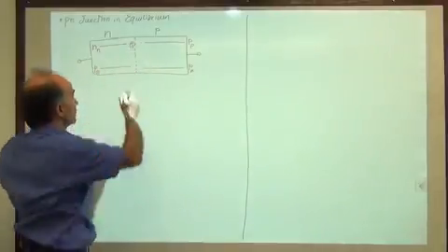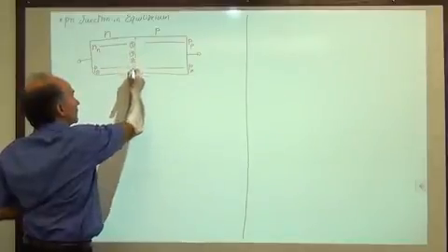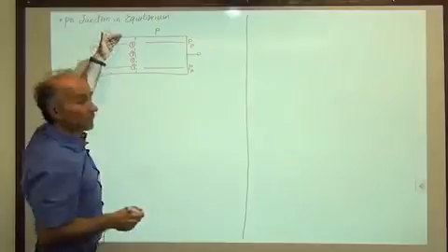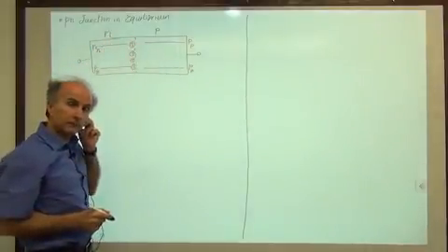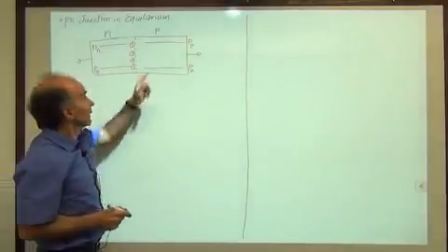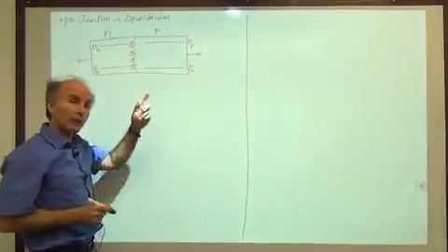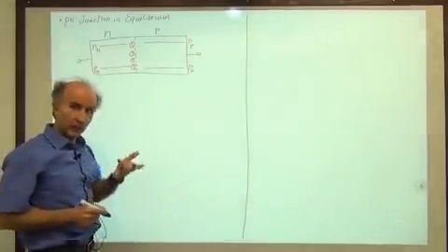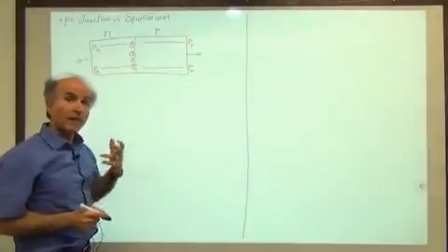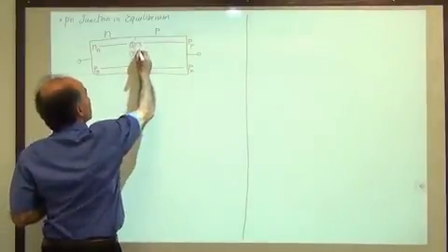So this continues. So we form lots of positive ions on the left side because lots of electrons are leaving the left side to go to the right side. What happens to the right side? Well, lots of holes are going from the right side to the left side. Every time a hole leaves, in fact, it is filled by an electron, so we form negative ions. So we have lots of negative ions here.